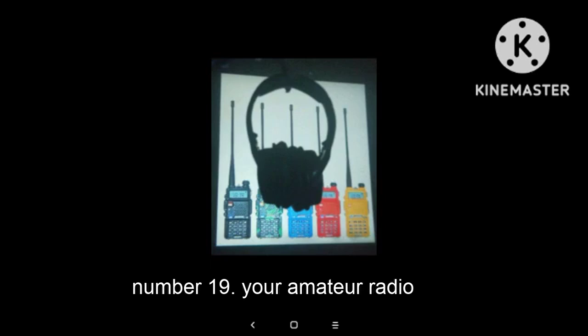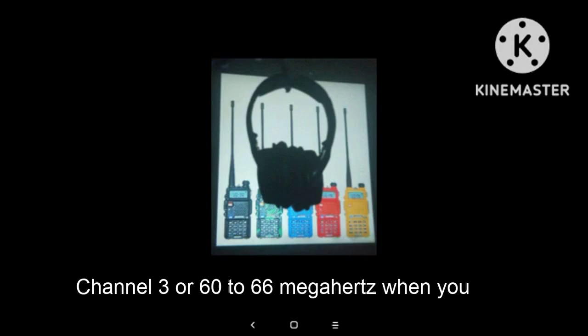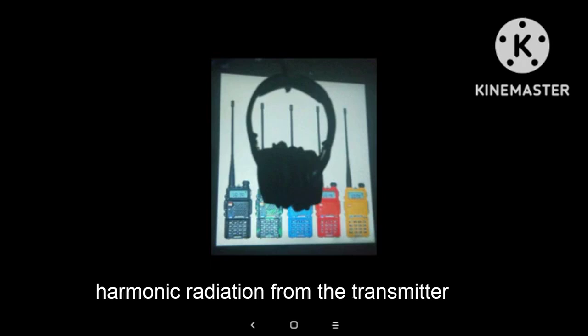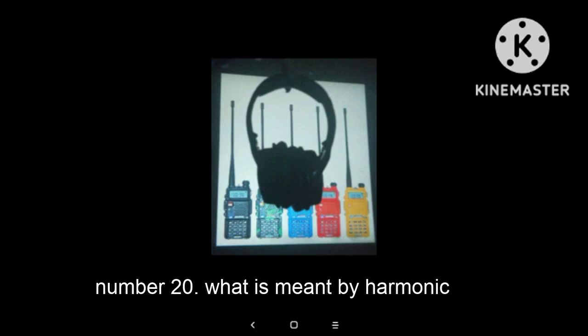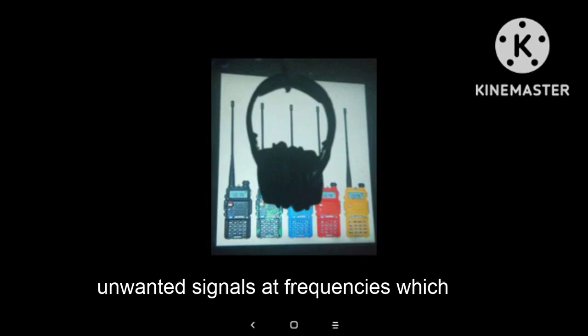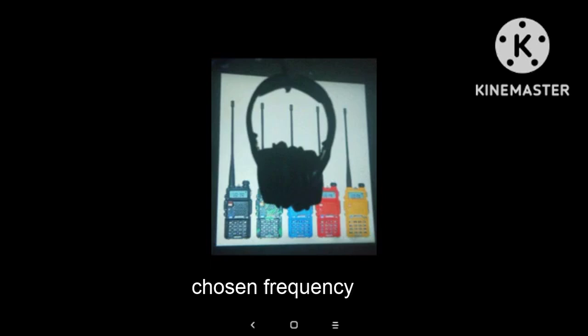Number 19. Your amateur radio transmitter appears to be creating interference to the television on channel 3, or 60 to 66 MHz, when you are transmitting on the 15-meter band. Other channels are not affected. This is most likely caused by harmonic radiation from the transmitter front end. Number 20. What is meant by harmonic radiation? Unwanted signals at frequencies which are multiples of the fundamental or chosen frequency.